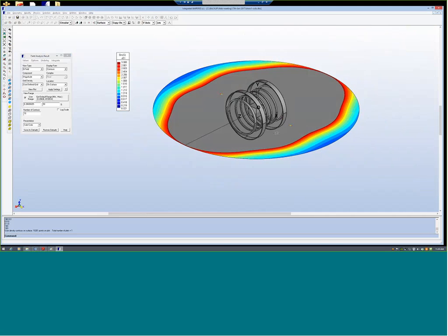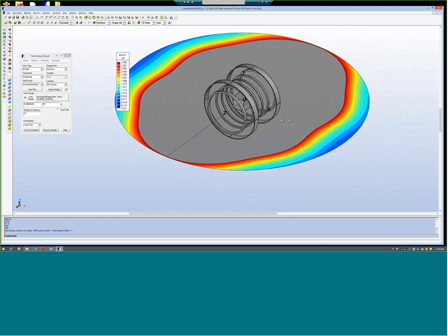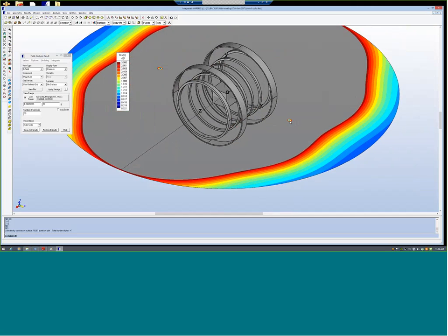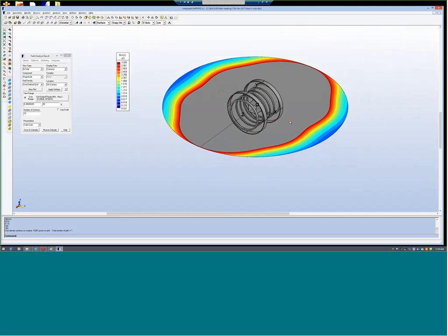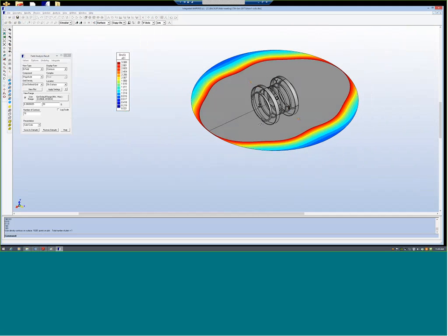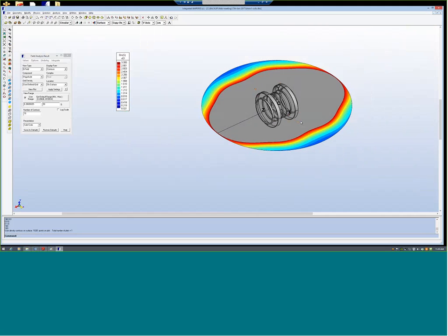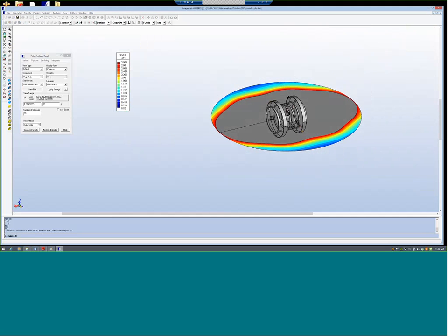But to get 30 Gauss, you don't have to go 3 meters from the side. It is maybe half of it, maybe 1.5 meters or 1.6 meters. There itself, we are getting 30 Gauss. These are the two spots, but the rest of this gray color indicates the fields are less than 30 Gauss. This is the use of having a contour plot.